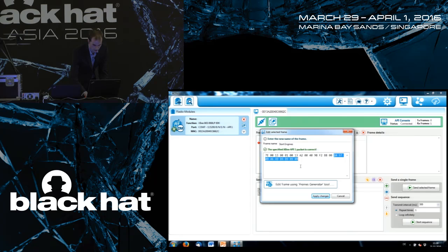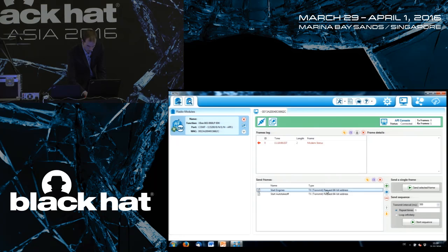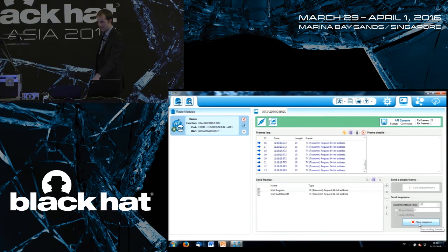So this is the static preamble. And the last 6 hex chars here, 898989, this is the command for start the engines. Okay. And we'll just loop infinitely through this command and start the sequence. And now this chip is sending out the data to the UAV, and the UAV is receiving this data and is performing the action.